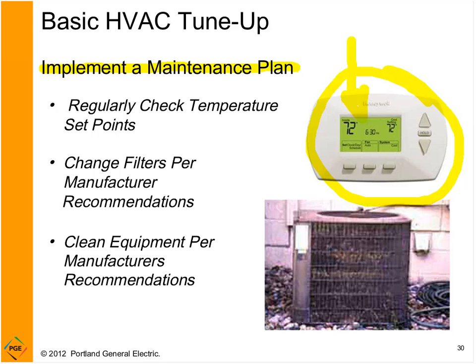So program it, and don't just program it and forget it. You want to program it and periodically check it, because I don't know about you, I hear tons of complaints about building operators who struggle with the building occupants modifying the set points and changing the hours of operation. And so like I said, just follow up and find a spot that you want your temperatures set to and nail down the hours of operation that you want to have, and then check it.